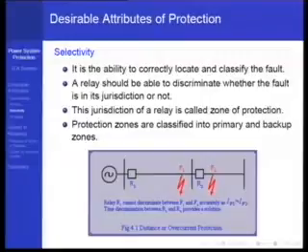You cannot just duplicate protection systems at the same place and get that kind of reliability in protection as a remote backup achieves. So remote backup is a must, even though zone 3 has its own disadvantages of picking up on low voltage conditions and so on. So that part is accepted, but throwing it out per se itself is not a solution to the problem.